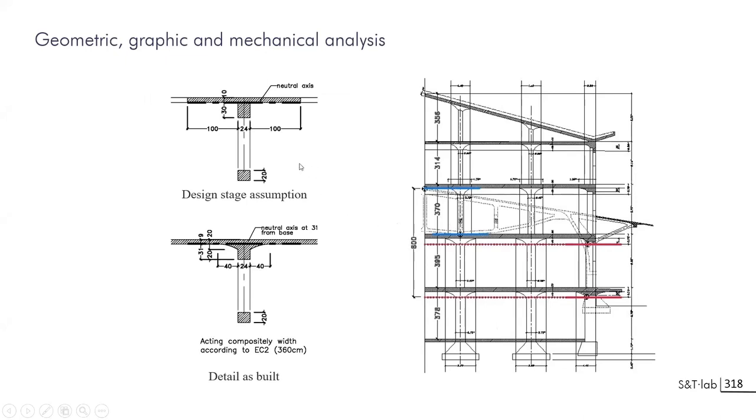You see that Maya with the first sketch is using a very simple mechanism. You have two flanges of 1 meter, you have a thickness of 10 centimeters, and you need a rib below of 24 centimeters on the horizontal line and 30 on the vertical line to get the neutral axis just at the limit of 10 centimeters.